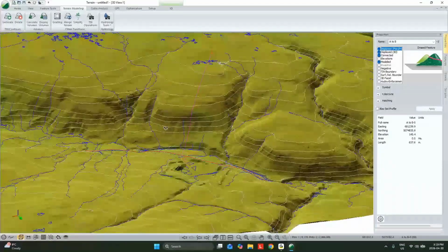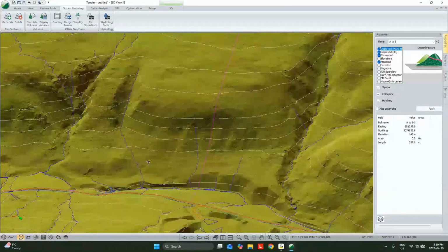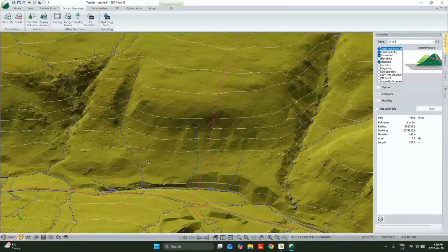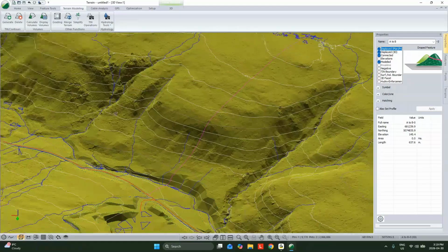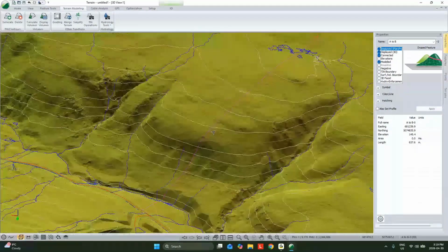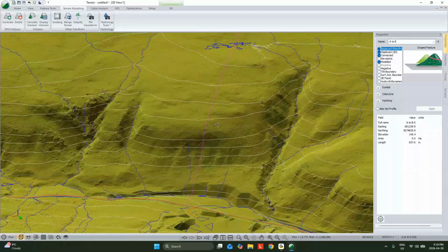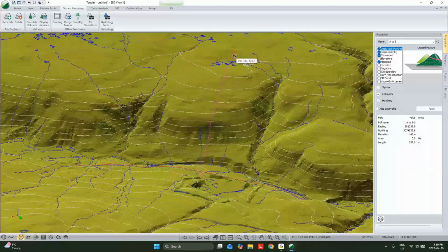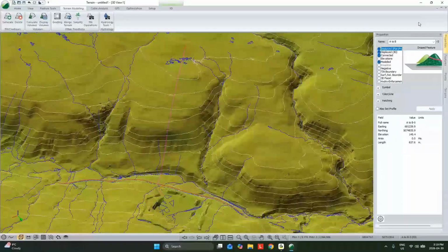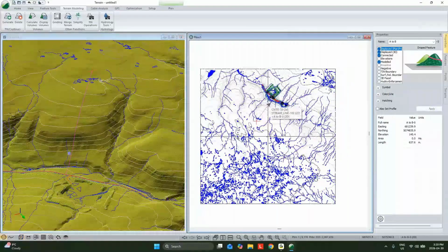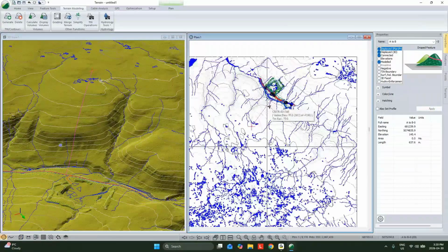Well, if I was doing this manually and hadn't seen the data set before, my knee-jerk reaction would probably be coming off here, crossing this, switch backing up, try to get on this bench or this terrace as quickly as I can and get to it that way. So we'll keep that in mind, and I'll let folks make their best guess. But of course, a big tool that we have is Path Explorer. So here, rather than going through that iterative process and kind of manually deciding where we want the road to go, which we will cover next, we'll take the optimization tab.